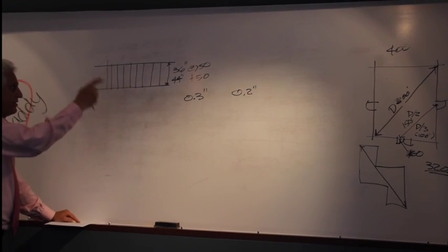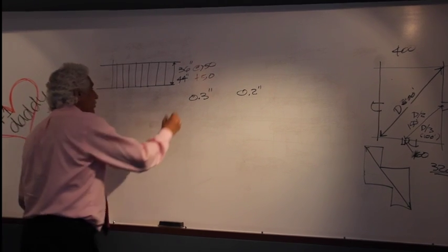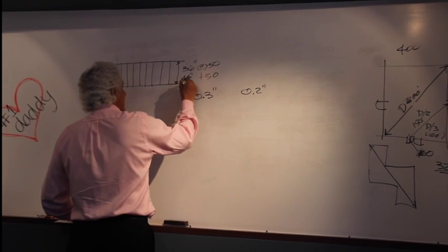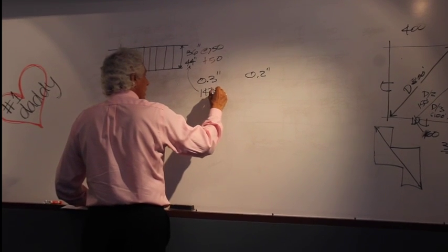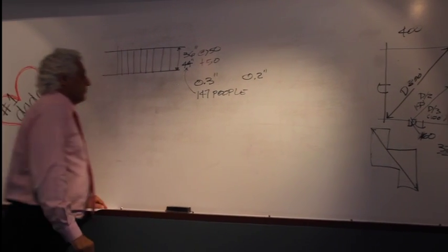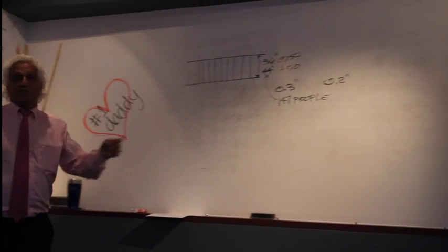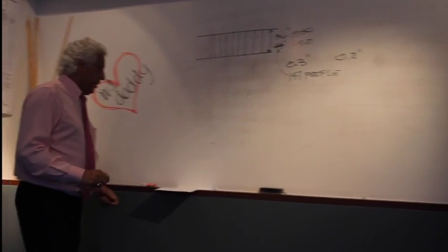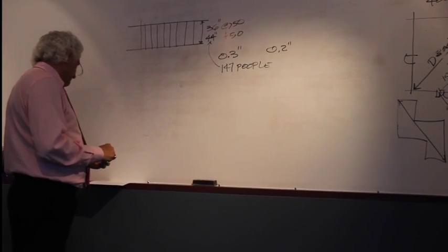Where the corridor, if you remember, was 0.2 per inch. It's a matter of dividing that into the width, and with a 44-inch width, you can have 147 people traverse that stairs. If you have more than that, then your stairs become wider: 5 feet, 6 feet, 8 feet, whatever you have the capacity for to deal with the number of people that are there.